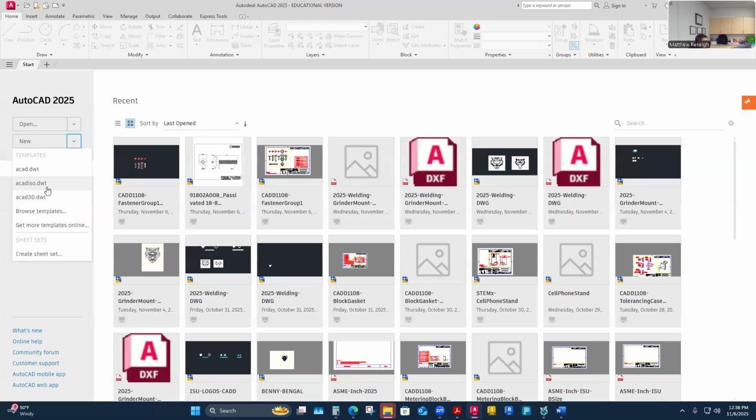So I think of going from this parent, a DWT file, to a drawing file, which has all of my data. It's really a big file type. That's not what I want to send to a machine to cut, because there could be some overlying lines that I don't want the machine to interpret. So I simplify that down to pretty much single line layer drawings, like your mechanical drawings used to look, just one layer. In fact, I even get rid of all the hidden lines and center lines and everything. I just have the lines that the machine is going to cut. And that's called the DXF file.